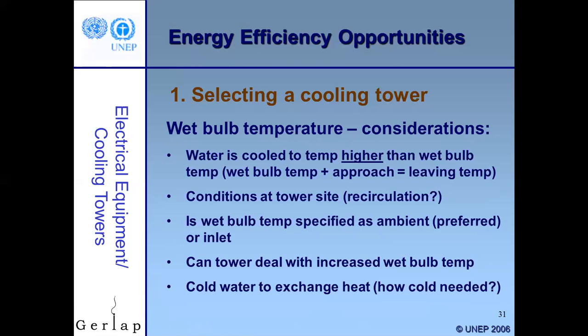And then, of course, recirculation. We're concerned about the prevalent wind conditions and directions and all that sort of thing. Make sure we're not blowing this blast up against a building that won't let it escape, etc. Things like that can happen. If you expect some recirculation, you have to upsize the tower to make sure that it can handle it.